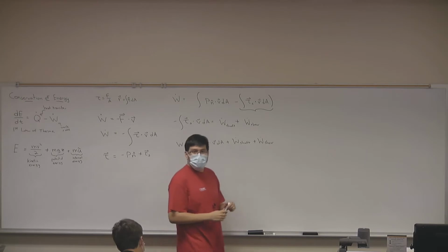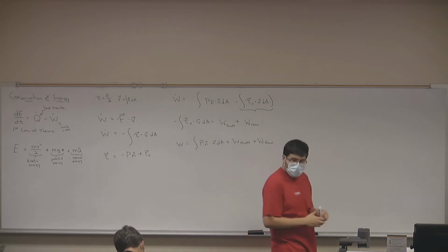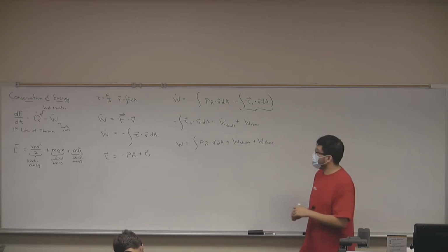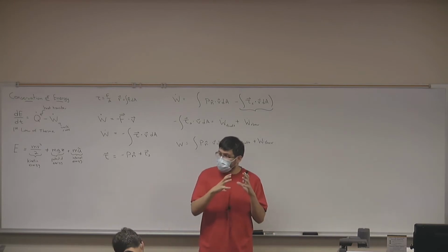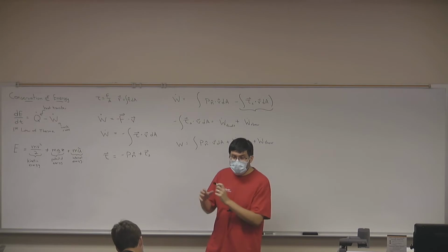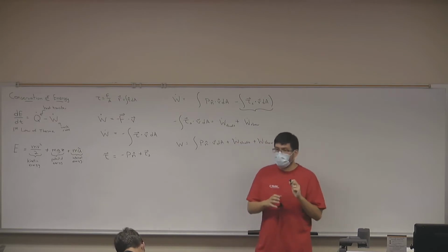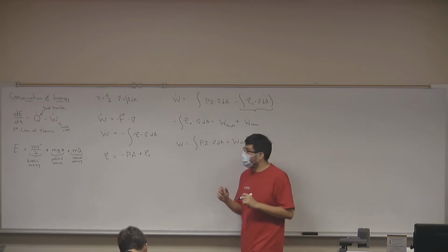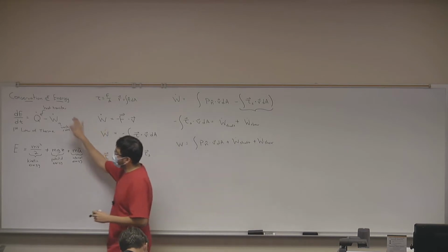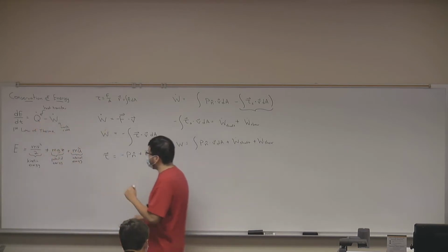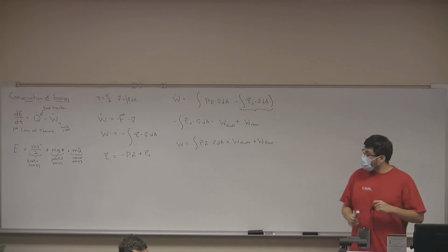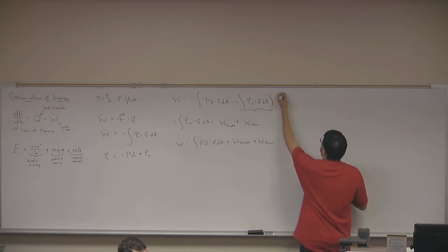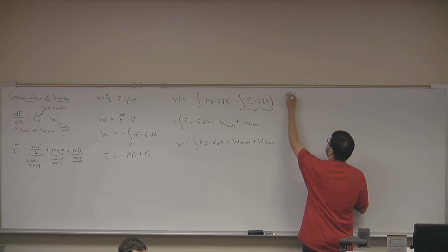Control volume is focusing. Yep. Thank you, Gabriel. Control volumes focus on locations in space. Systems follow fluid particles, so follow fixed sets of mass. This is an equation that applies for a fixed set of mass, but I would like to apply it to a control volume, to a location in space. And the way I'm going to apply it is by using the Reynolds transport theorem.